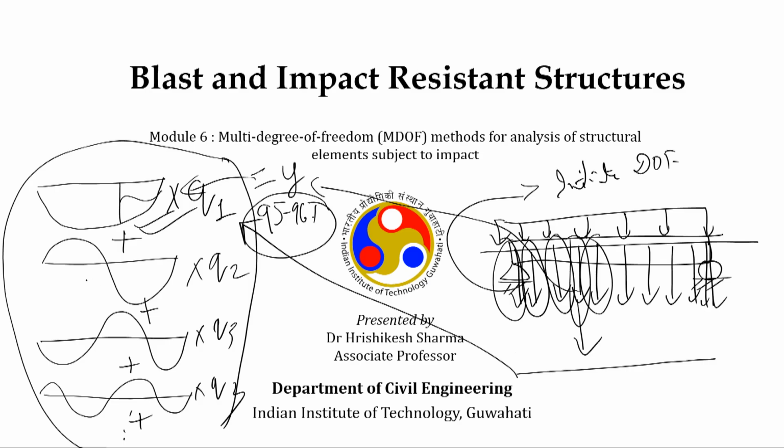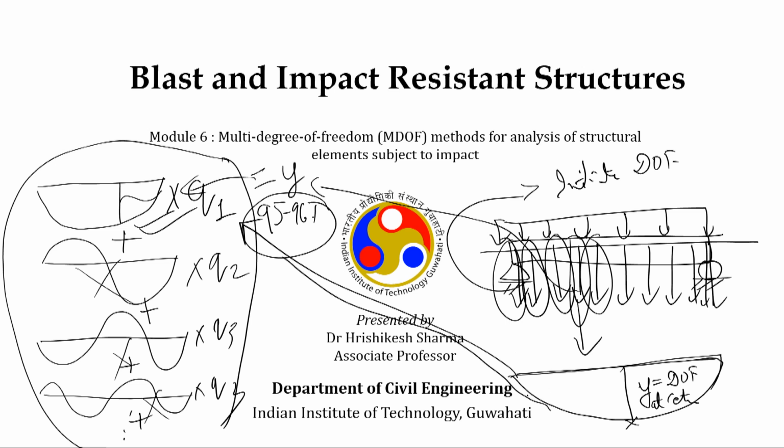So, we ignored the contribution from the other modes and substituted our system with a single degree of freedom system. We chose the point where the maximum deflection occurs, that is y at center, and took only the first mode. Though the accuracy is lower, the calculation is fast. This was the single degree of freedom system analysis.